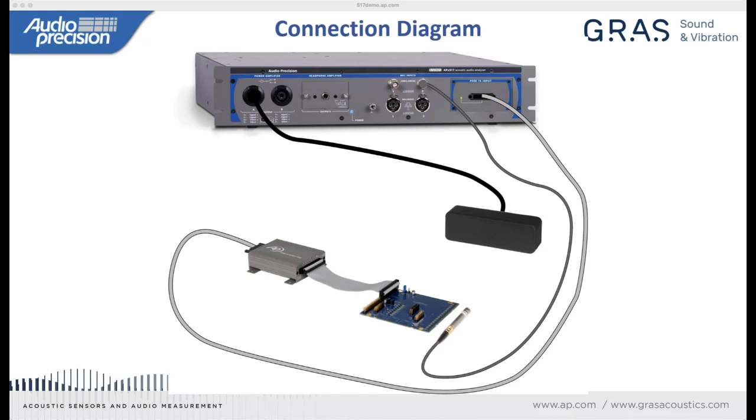The question of what source speaker I would use, and I'll talk about that some more when we get to the hands-on, but the preconditions in my mind are the frequency range over which you need to measure your microphone and the sound pressure level at which you want to be able to measure your microphone.